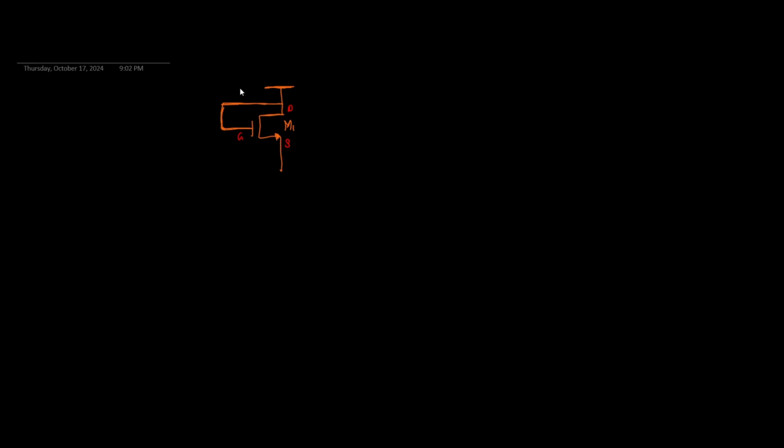So when we connect the gate and the drain, Vg equals Vd, right? And this is VDD, this is VSS. Okay. So to maintain saturation region, we know that for NMOS we should follow this criteria, right?